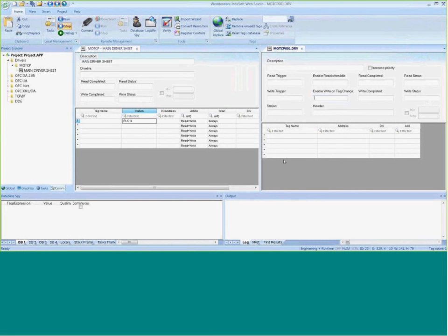I'll give you an example on some pipeline applications, some pumping stations that are out remote. You might want that to be a 24-hour cycle. For example, it wakes up at 2 o'clock in the morning, bursts its data, validates it, and then shuts itself down.